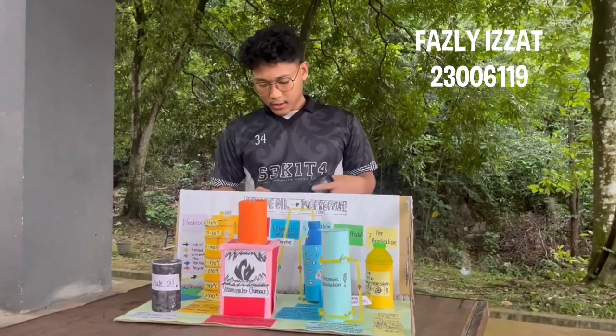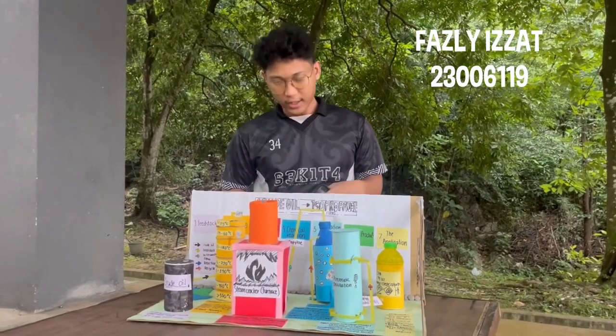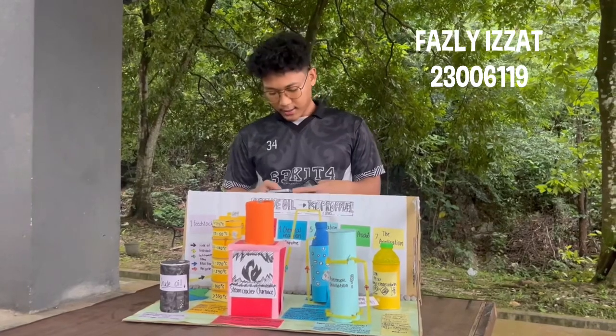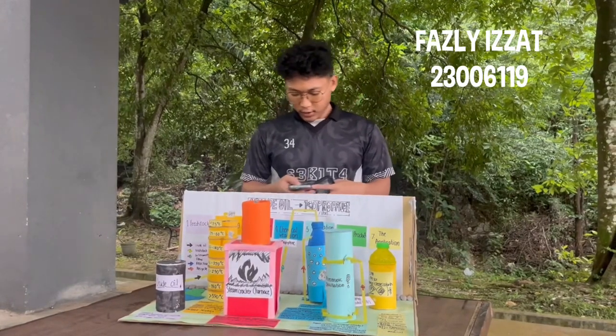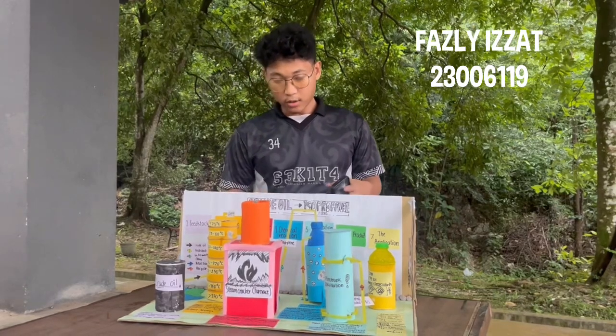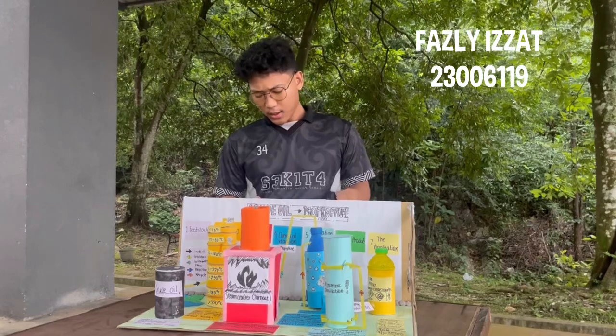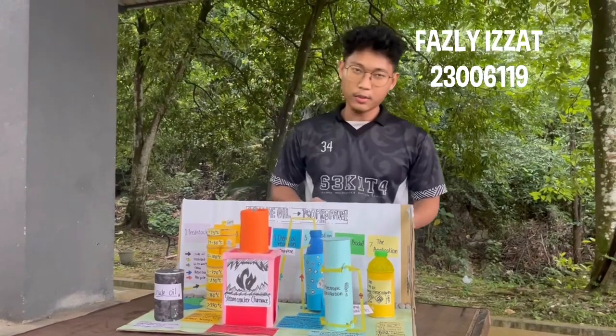To break this thermodynamic boundary, we implement azeotropic distillation. We introduce an entrainer solvent such as cyclohexane into the column to alter the relative volatilities of the components. The purification operates efficiently at atmospheric or reduced pressures between 80 to 85 Celsius. In our 3D model, this critical phase is represented by this light blue column.